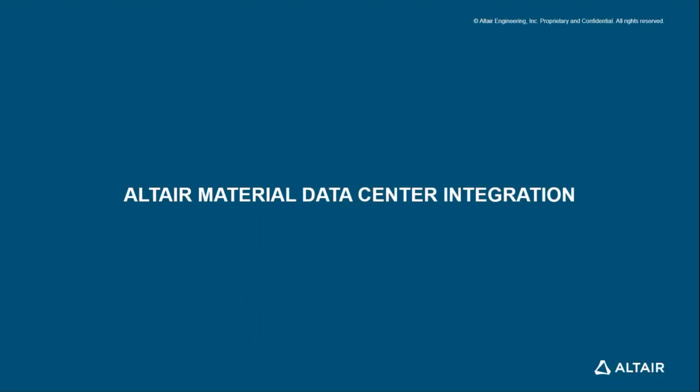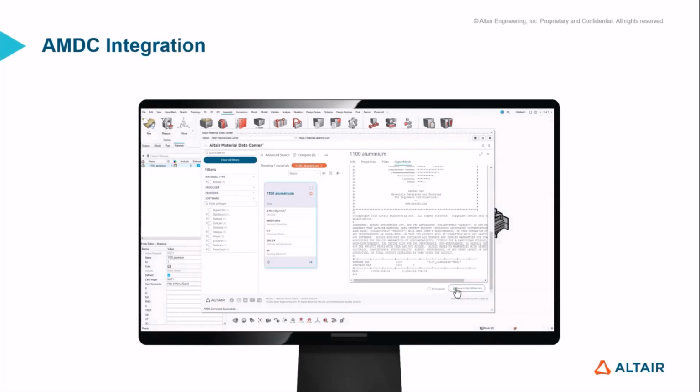The next one, with this, the model build portion is over, and the next one is AMDC integration. We have a major update to AMDC integration. When it comes to the AMDC integration, there was a major shortcoming that we were creating duplicate materials in case the names match. So you have, let's say, queried for 1100_aluminium, and when you load it from AMDC, we were creating 1100_aluminium.1 if the IDs are not matching.